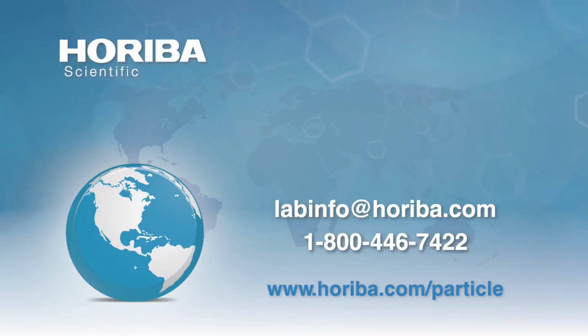But in the light of the talk that I just gave, the solid crystals now become quite interesting, because are the crystals blocky crystals? Are they plates? Are they needles? Because depending upon the morphology of those crystals, you will get either one or two peaks in your apparent PSD, and so you have to apply the techniques I was just talking about in order to get the crystals.